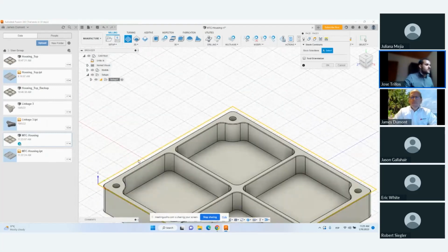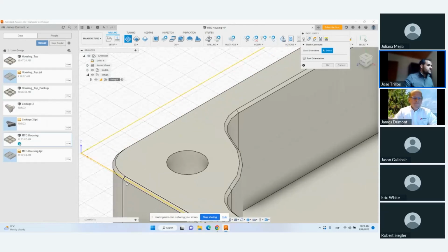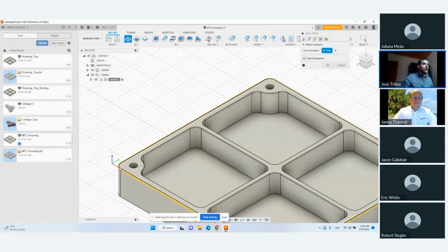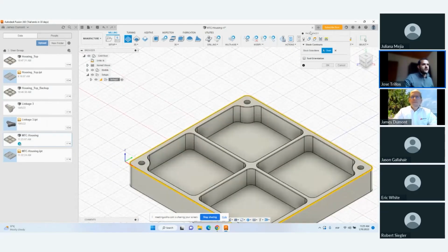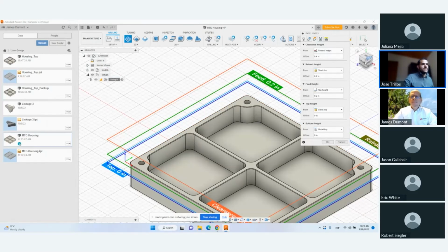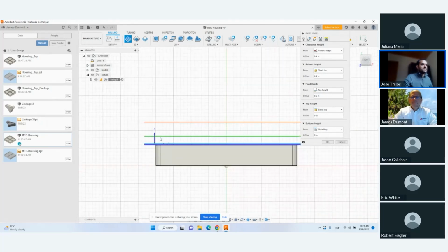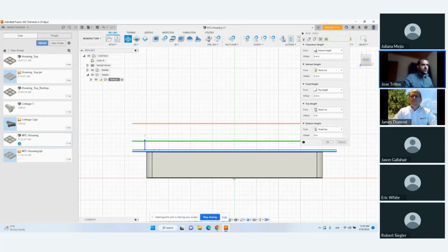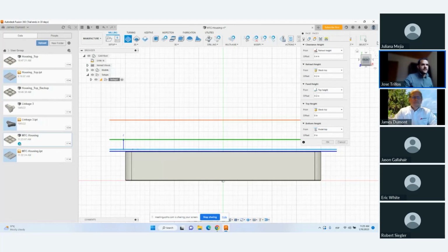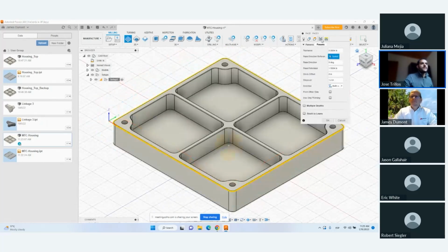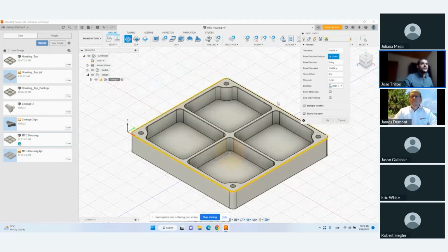The stock contours. Well, I can select the outer one. Control the height. Let's say these are going to be my heights, where the tool is going to be when it feeds, when it starts rotating faster, what's the top, what's the bottom, etc. Let's say I have in here the over stock offset.